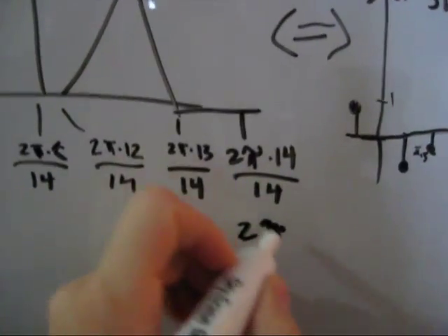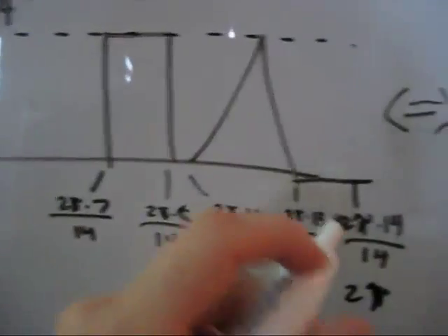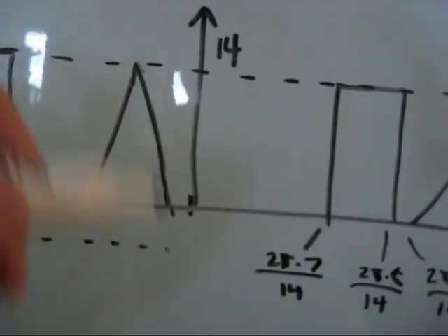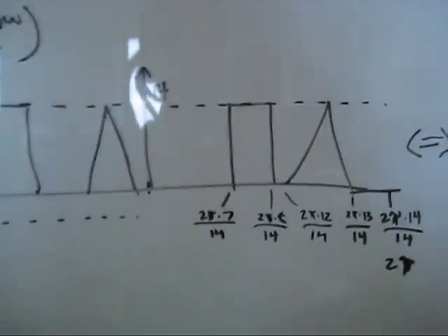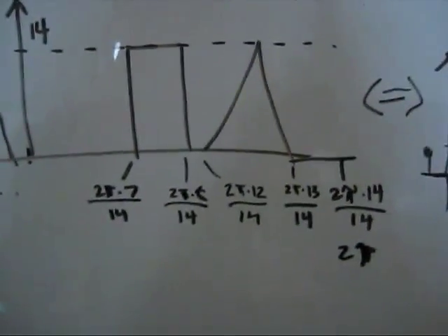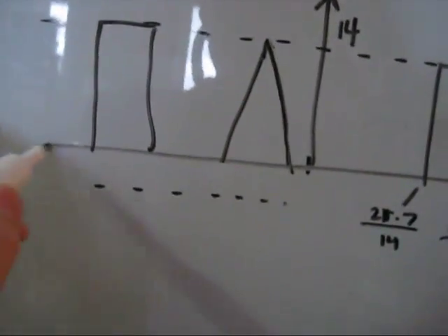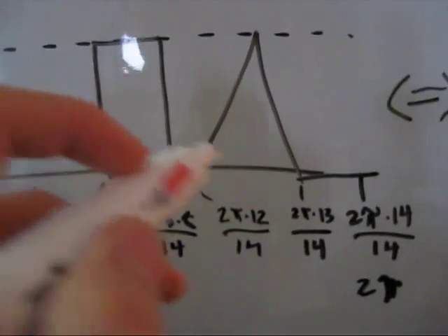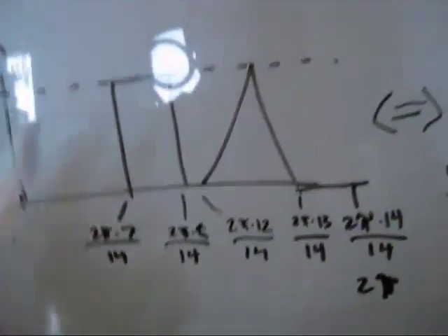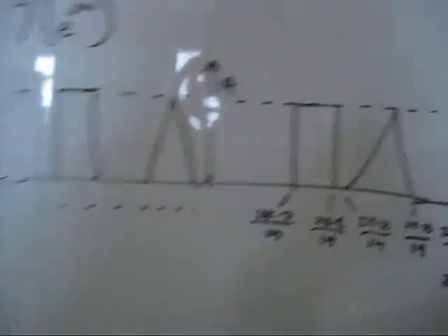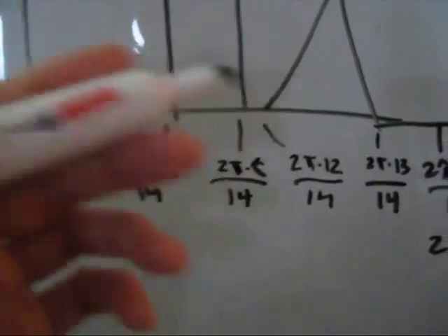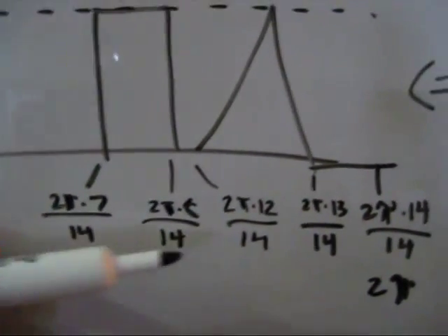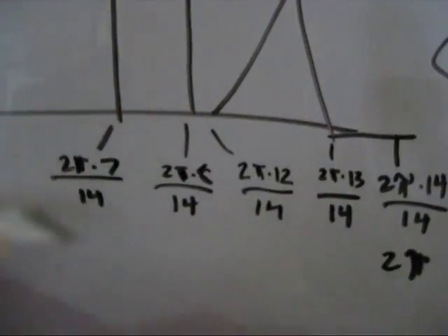So you've now got high frequencies located near your sampling frequency here, and you've got low frequencies now located near 0. And this of course goes off just like before. So those are all the negative components. You want to get rid of those and keep these, and then you want to take these and put them back into the real world. So how do you do that, right? Well, that's the simple part. You put it back through your digital to analog converter, sampling at 14 hertz.